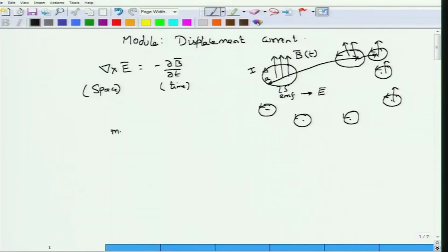Am I looking at some relation which would tell me there is a quantity we can call magnetomotive force, just as you had electromotive force, which was the line integral of electric field between any 2 points? You can similarly talk about the line integral of H dot dl and call this magnetomotive force, in analogy with electromotive force.